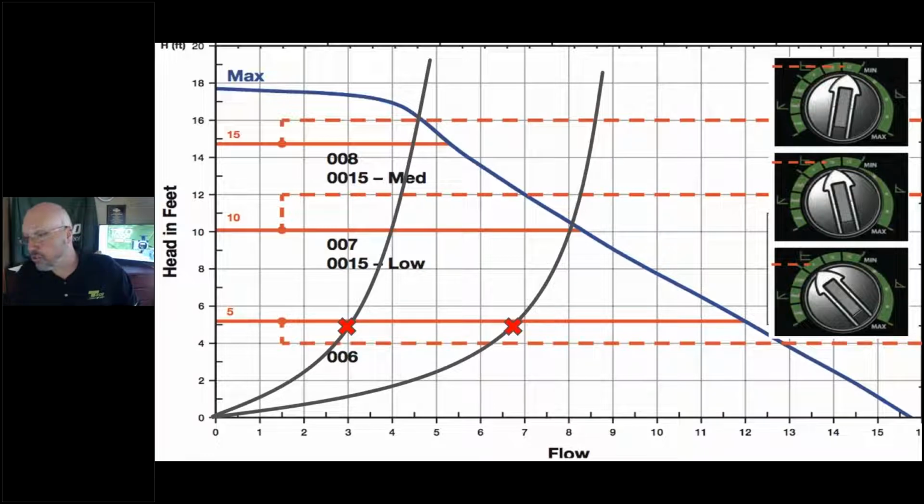I do see a question from John coming in. Do those pressure drop calculations relate to copper pipe or PEX? Typically, those are your safe, trouble-free copper numbers. PEX, they'll be a little bit lower. And you would have to take a look at some of your PEX manufacturers to get the more accurate numbers there.